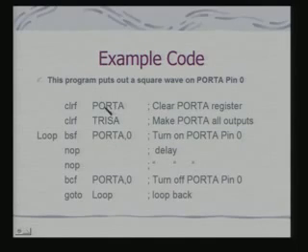Now, typically each port has a register associated with it, and you clear the content of the register, because if you want to write something onto the port, you would ideally like the content to be first cleared. The next thing is, these ports can be I/O ports, that means each pin can be configured as an input pin or as an output pin. If you are doing that, then I need to pre-program that port and each pin of that port.